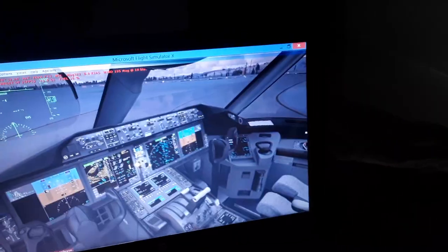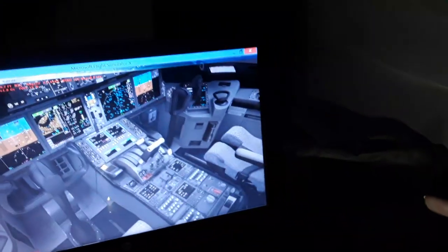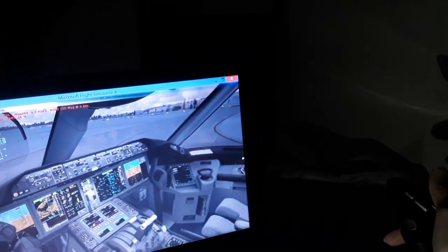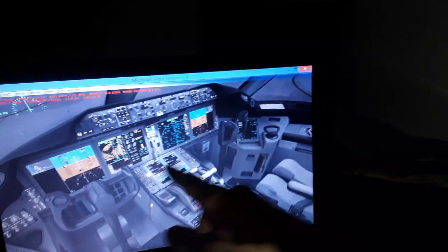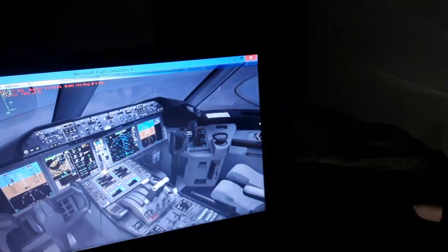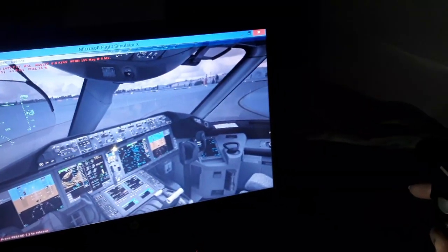So this side stick left and right priority button, and you use dual input in the Airbus also. And in the Boeing both flight controls are interconnected in every movement, also the rudder pedals. Unless you have a failure or you need to take over, you use an override force for either side flight controls, the captain or the first officer.